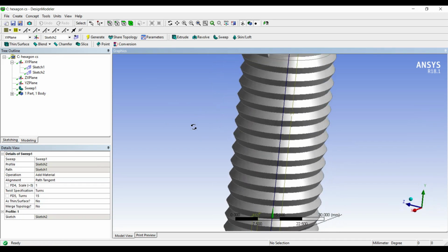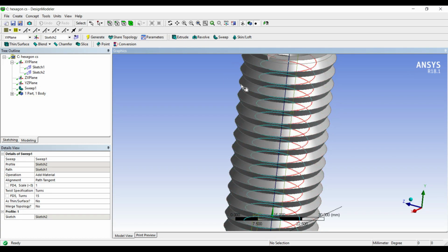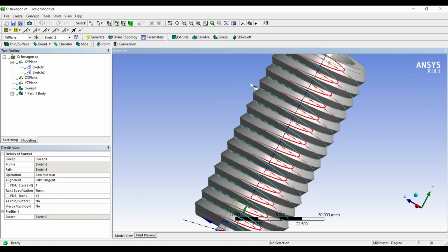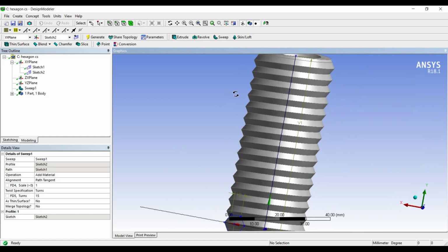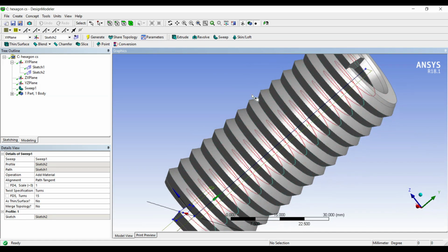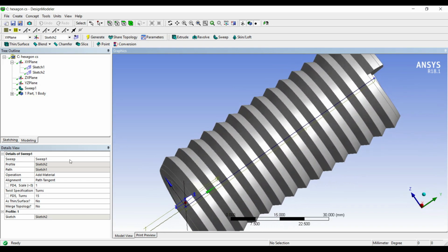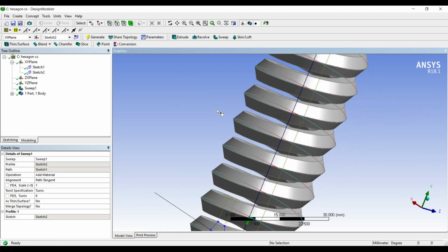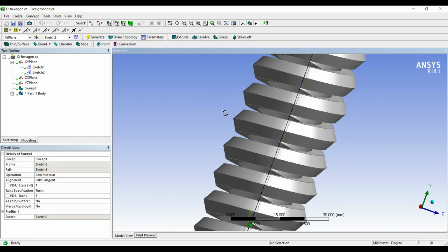You can see as the geometry changes, the spring is going to have very less pitch over here, so its load bearing capacity will reduce, and also it will not be able to absorb the shock so much. So if you see over here, in fact there is an interference also between the surfaces, which means I cannot choose 15, so I will have to choose say 12. I can still see interference, so I'll make it 8. Now I get some spacing or some pitch as we call it.